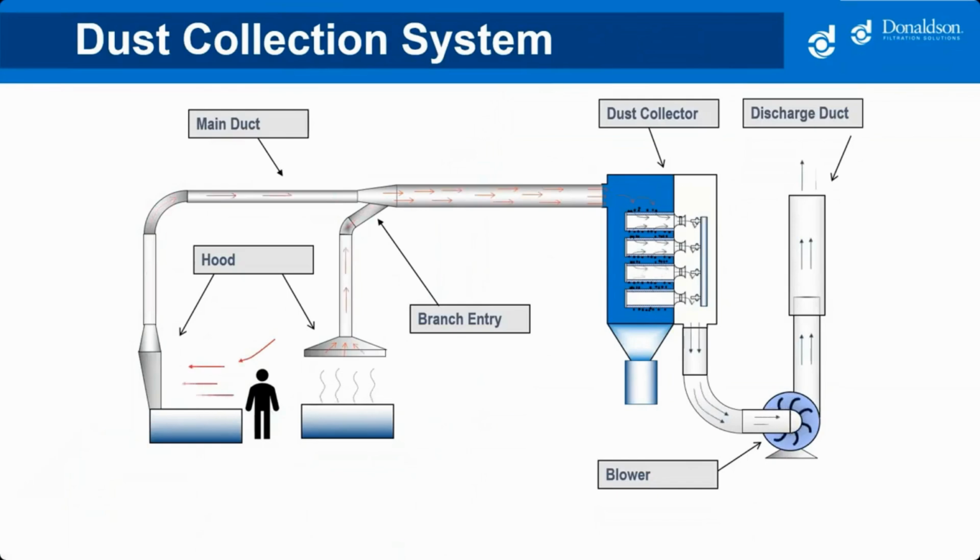discharged to atmosphere. It's very typical for these types of systems to have the fan on the clean air side, so you're drawing the air through the negative of the whole system through the filter. If one component is poorly designed, the whole system is affected.